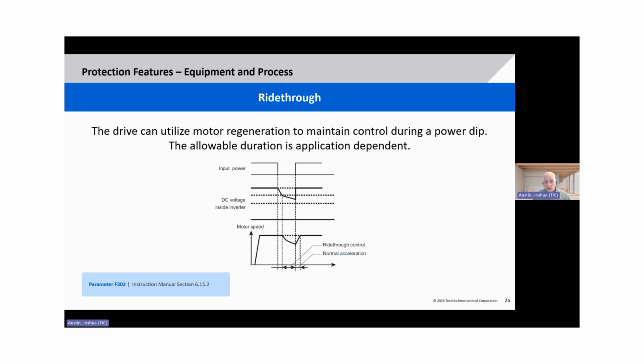And so the only thing with this is it's very application dependent. The VFD itself has capacitors inside the drive, so we are able to store a small amount of energy inside the drive, and then we're able to control that motor where we're trying to cause the motor to regenerate energy to maintain the voltage inside the drive with our capacitors and our control section, so that we can maintain control of the overall process.